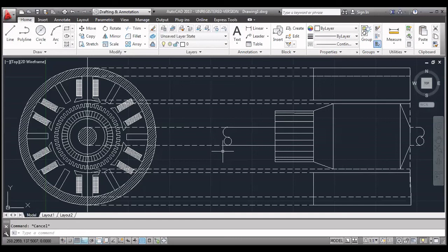So one class I'll take core type, and you draw like this diagram and label all the parts, and you can put the dimensions. Without dimension we have done, just write the dimension. What is the width of a pole? What is the height of a pole? So it is understood that you know what is commutator length. This is commutator length, right? So left part is your end view and right part is your elevation part. So this is all about today's class.